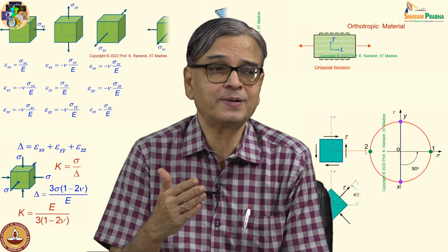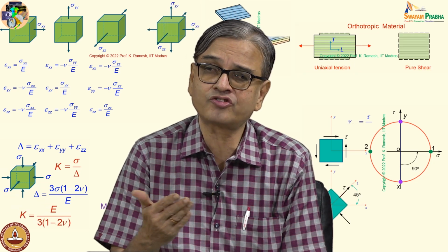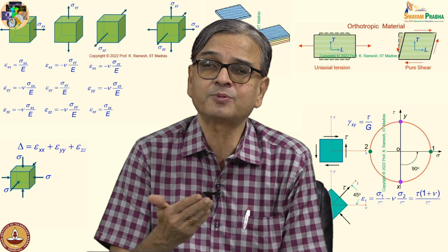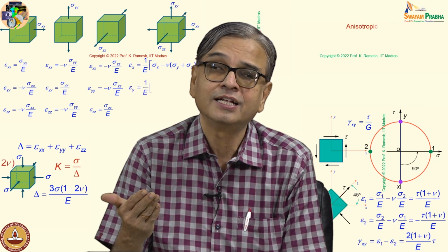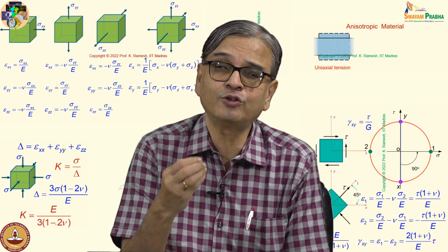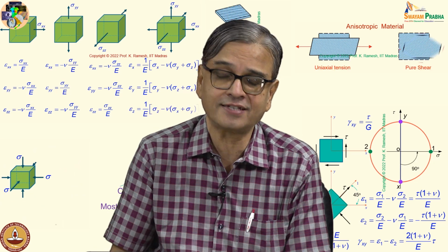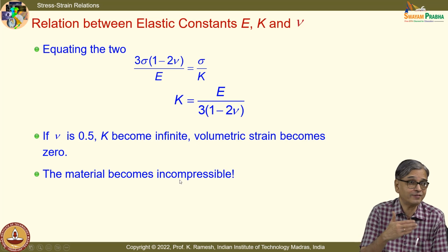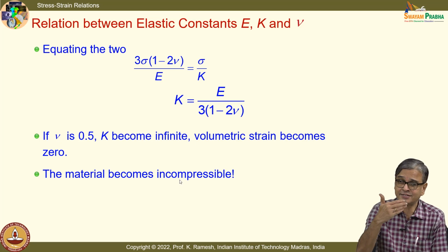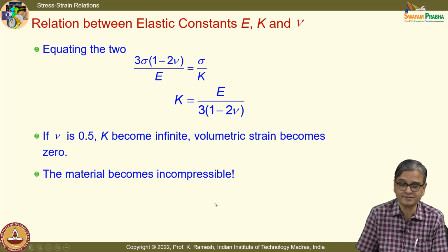One of the aspects we have also looked at when we discussed strain gauges is that when the material becomes plastic, the Poisson ratio approaches 0.5. So, one of the idealizations they make in simple plasticity theories is that the volume remains constant. That is one of the conveniences in simplifying the material model that comes from a discussion like this.